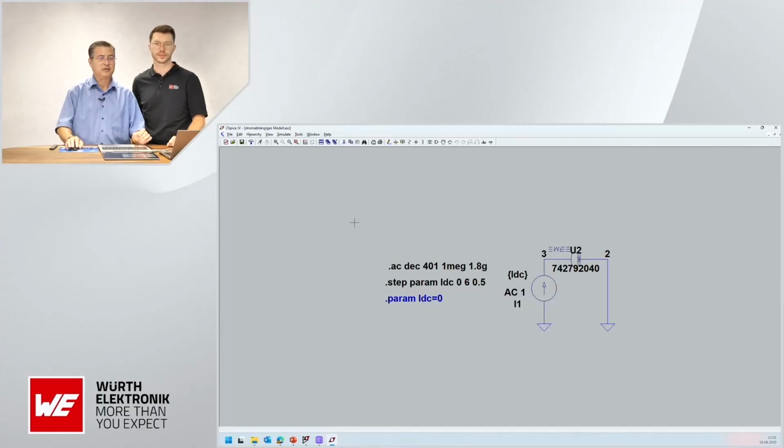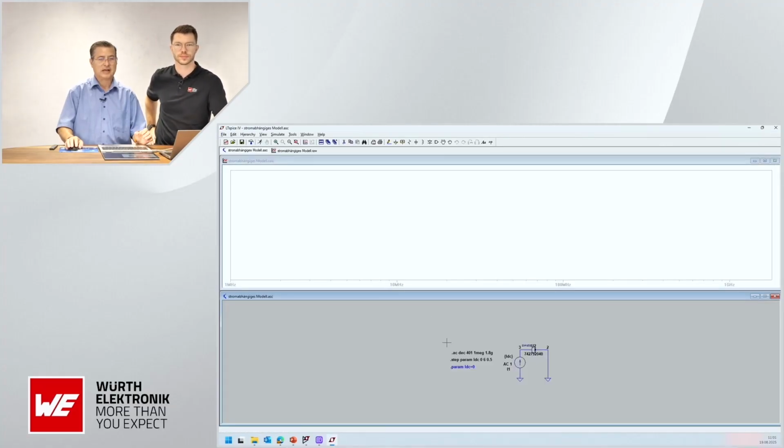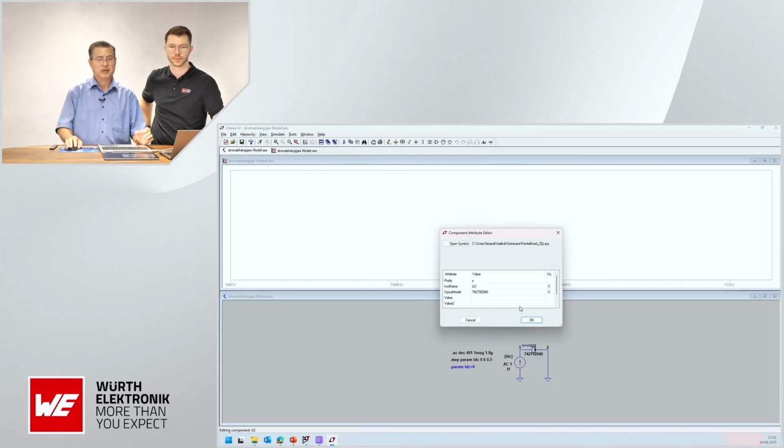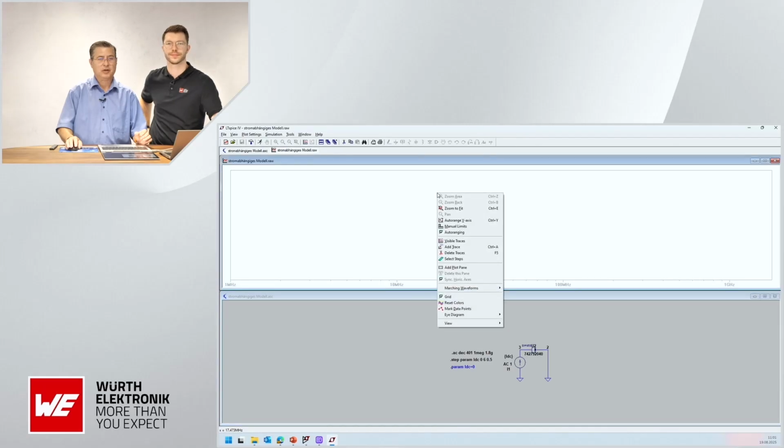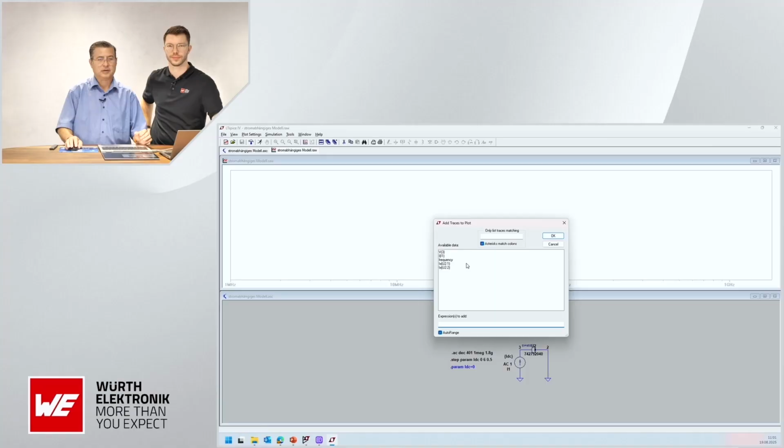You can choose the ferrite bead there and even simulate its saturation behavior. If you choose the model Z in brackets I, this is a model for our ferrite beads, we have these curves, and you just add a trace, and if I know the voltage, I divide the voltage by the current.